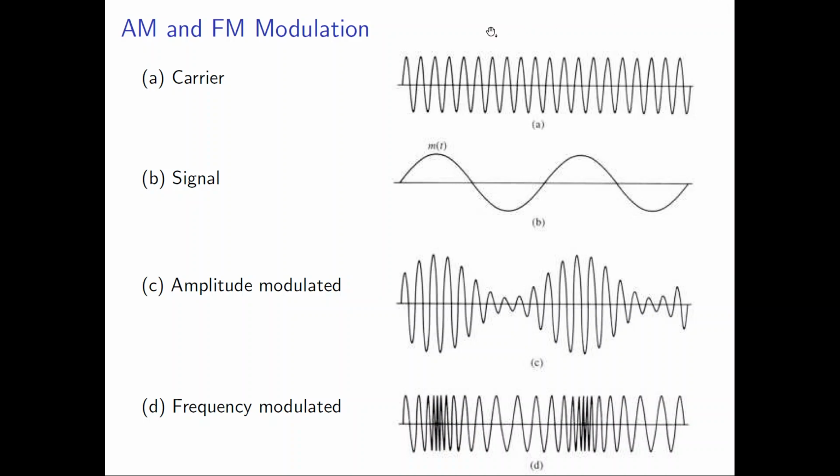Why does the carrier always have high frequency? Exactly, we don't want other people to listen, and we want to use practical antennas, and we want it to reach farther distances. So here, as you can see, the carrier shape changed based on the shape of the message. So when you get the amplitude, the envelope of this signal, you get the message.